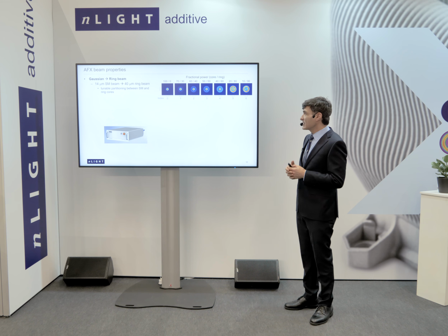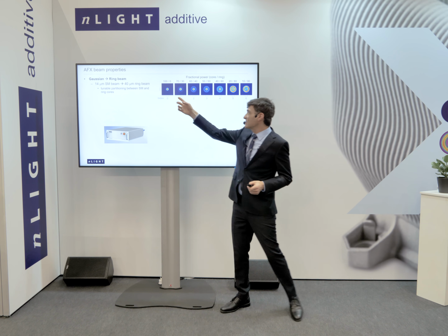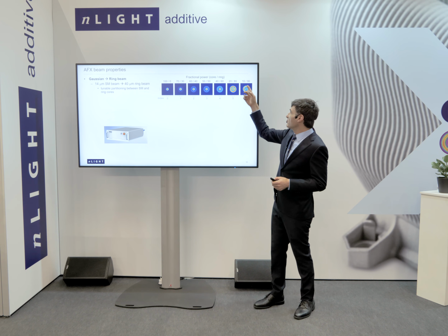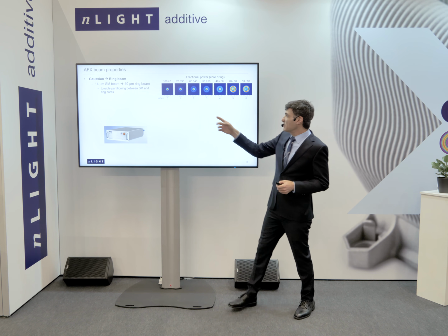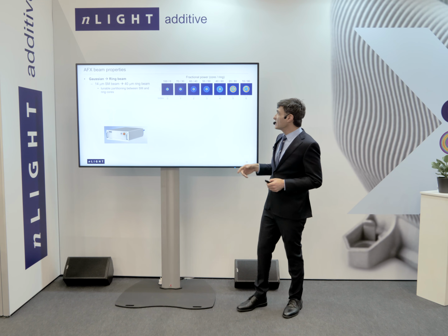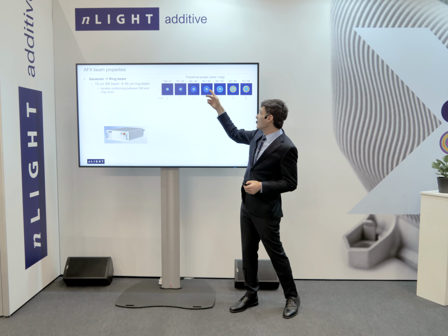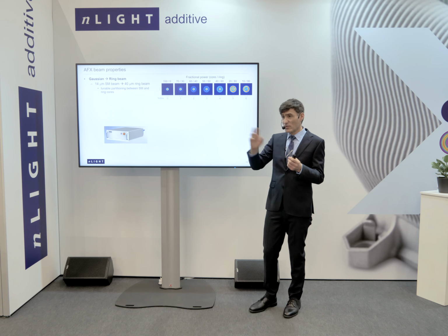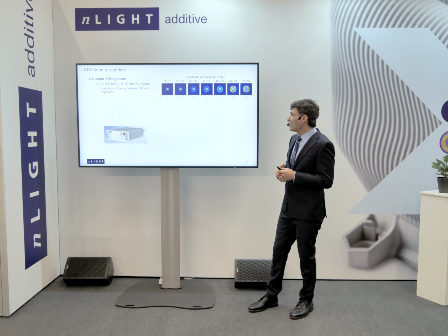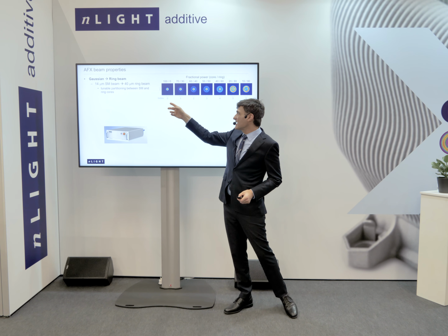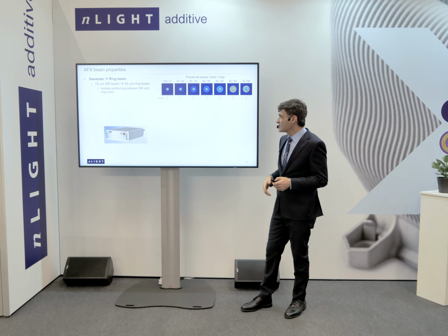So looking at AFX in particular, we have, as I said, the single mode core, and then a 40 micron ring, and the beam power is being divided up among these, 60% in the core, 50, 40, 20, etc., and the rest of the power in the ring. We call these different settings the index value from 0 to 6.